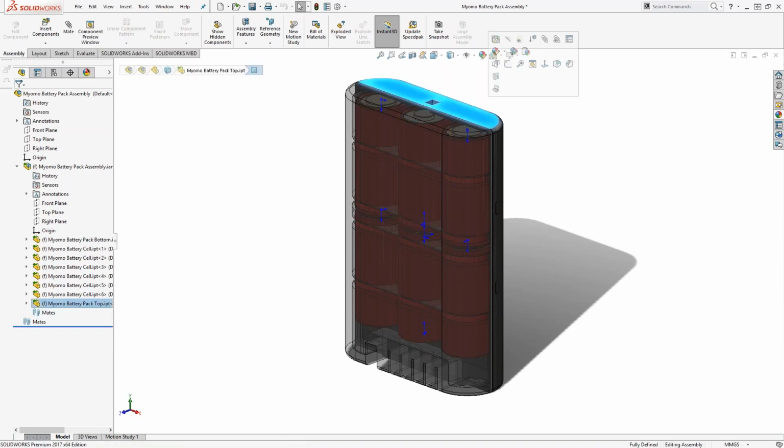If we say have this face up here, that face within the CAD software has a face ID, and SOLIDWORKS is keeping that face ID. So if you have things linked to that face, maybe assembly mates, or if you're modifying these data sets after the fact, you'll find that they will stay linked. So that's kind of just a really quick overview of 3D Interconnect and what it can do.